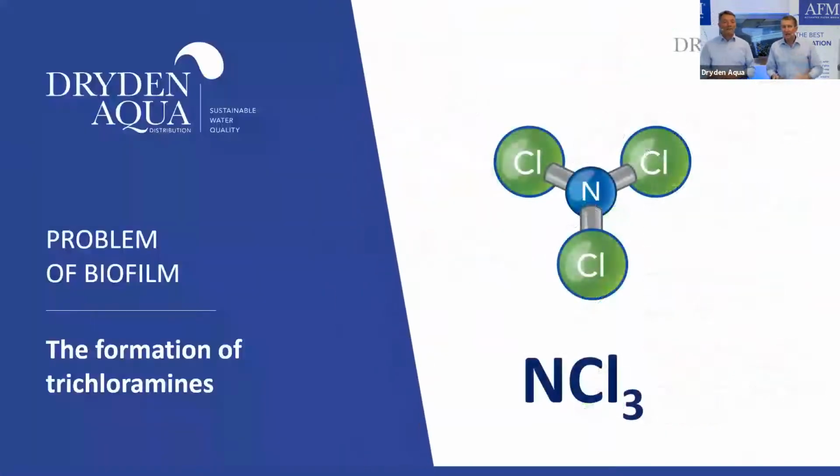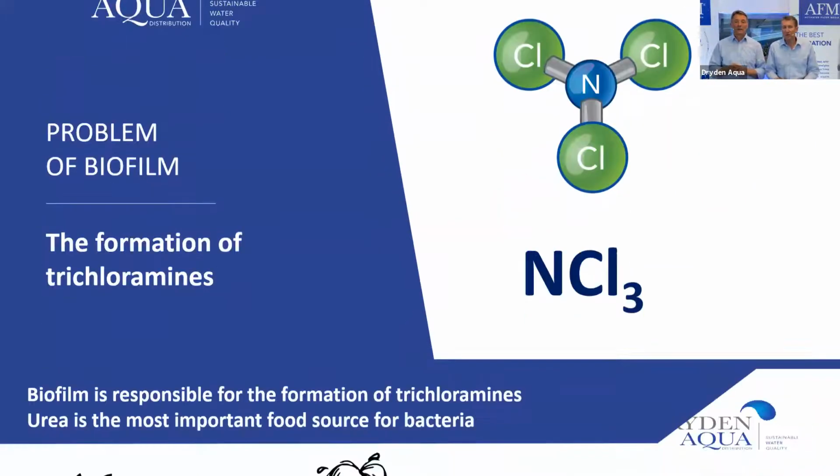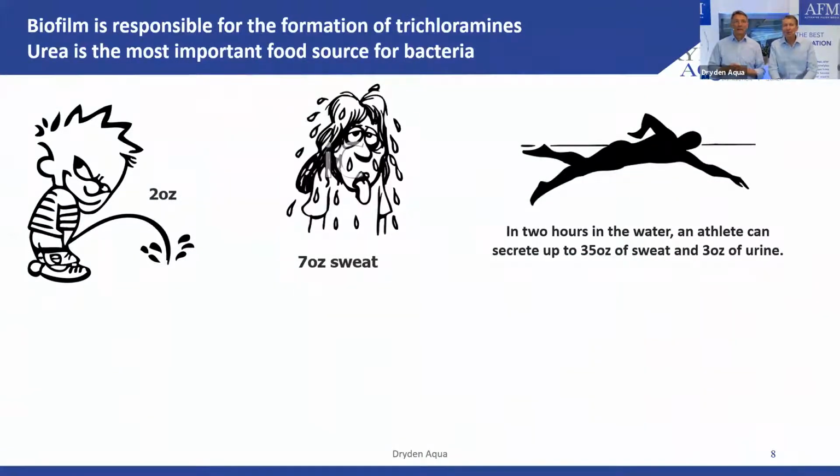The second disinfection byproducts we were talking about are the chloramines, especially the trichloramines. Let me add one thing before you come to the trichloramines. What is not the promise of AFM is that you will have much less total combined chlorine in an indoor pool. The promise is much less inorganic chloramine and especially much less trichloramine. Let's briefly talk about trichloramine.